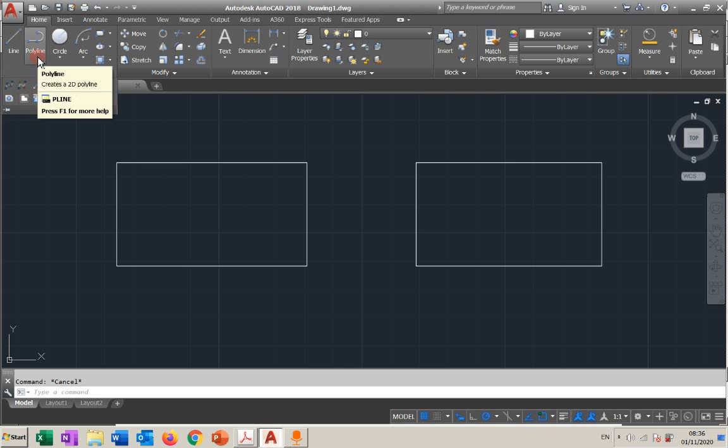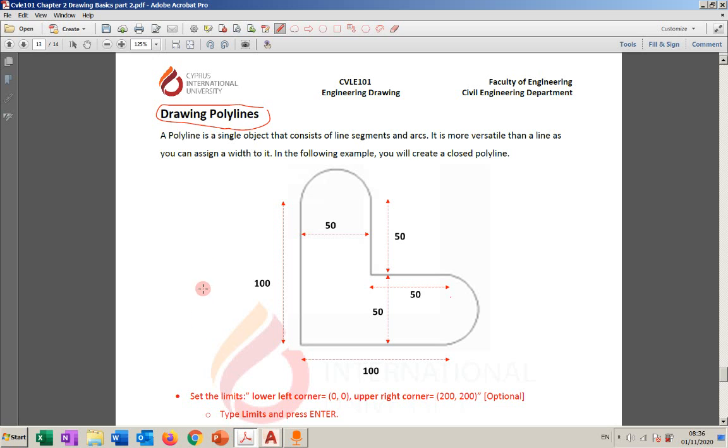We're talking polyline here. Now, polyline, what is it and why do we need to use polyline in AutoCAD? Now, the name of it, polyline, means that it's multi-line. We have it, multi-line, polyline, but at the end it will give you one object. So it's a combination of line and arc, basically line and arc. At the end it will show as one object.